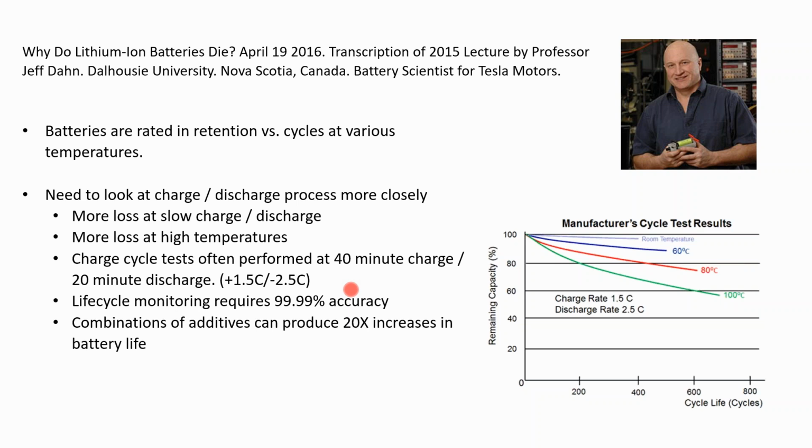And so we have this idea that rapid charging a lead acid battery is bad and you want to trickle charge it. That more has to do with the sealing of the battery itself and the temperature accumulation from the inefficiency of the process limiting how quickly you can charge and discharge that battery.